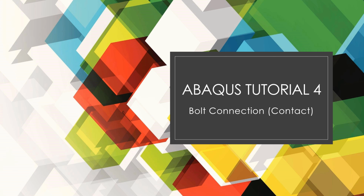In this ABAQUS tutorial, we're going to talk about something new, and that is contact. In our previous models, the only real complexity was that we had a hole in some of our parts. Now it's going to get a little more complex: we have a hole within our parts, but we also have multiple parts, a plate as well as a bolt. The complexity gets even greater because we have to define some contact between the plate and the bolt. If we don't define any contact between them, as you will see, they'll just go right through each other, which of course is not realistic at all.